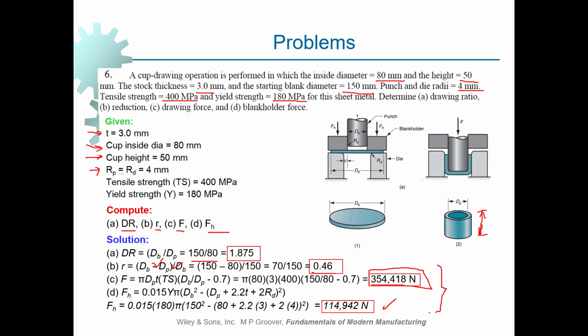Add the values of drawing and holding forces together, and on top of that, add an extra 10 to 20%. It is recommended to make use of hydraulic presses in drawing operations, so that the force is applied gradually by a hydraulic actuator.